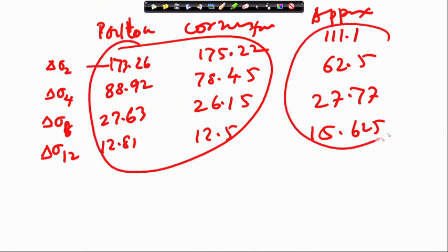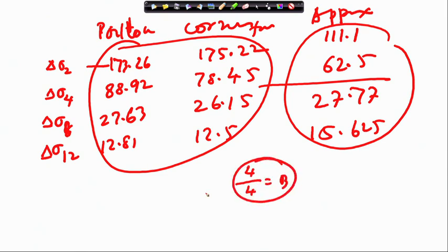This one has a little error, actually up to 4 meter. 4 meter is nothing but B, if I consider the dimension 4 and depth is 4. So, up to depth B the approximation is not very good, but at depths greater than B the approximate value is also quite close to the rectangular corner formula and point load formula.